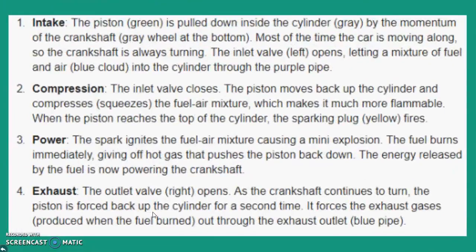This is basically the crux. These 4 processes constitute the whole burning process or the mechanism. So you have 4 strokes: the intake stroke, the compression stroke, the power stroke, and the exhaust stroke. Intake stroke is what takes the air-fuel mixture in. Compression is what compresses that mixture. Power stroke is what releases the power. And exhaust stroke is what releases the leftover exhaust gas mixture.